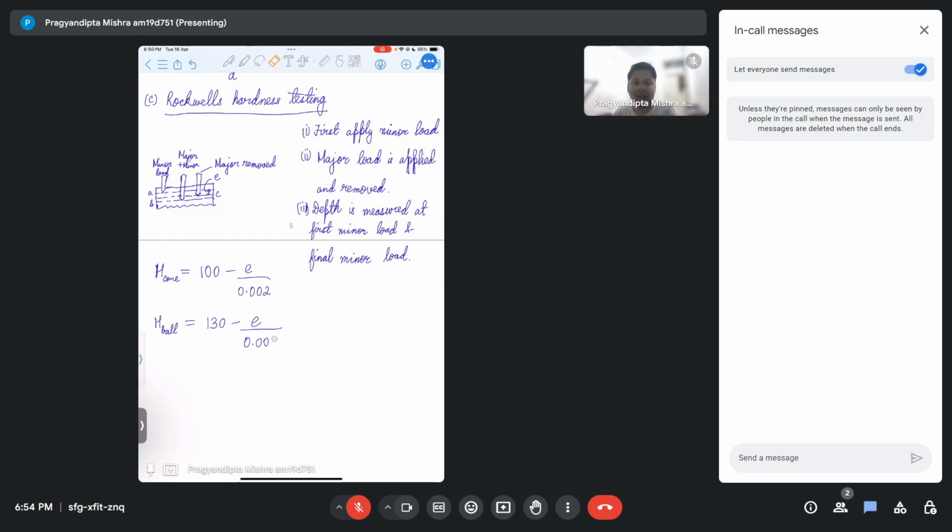It gives us a measure of how ductile or brittle a material is, right? Because if a material fails suddenly under impact load, the material is very brittle. The material might be very strong, but just because it failed suddenly, we can say that it is brittle. Brittleness and ductility have nothing to do with the strength of the material, but they also govern material behavior. You might have a very strong but brittle material that behaves well until it reaches its ultimate strength, but the moment it reaches it, it collapses immediately. It does not show a slow deformation compared to a ductile material.